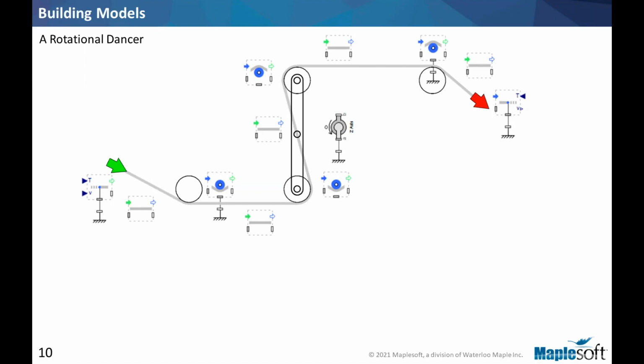We also need an offset for the rollers because they are not at the center of the pivot point. They have an offset with a certain length. So we'll select an option for add frame offset. We put half of that link to the one roller and the other half to the other roller, and connect them all to the top frame of our revolute joint.